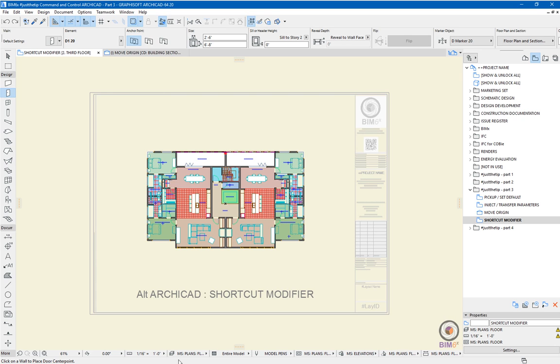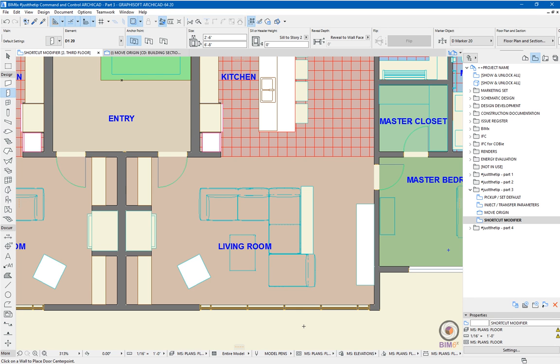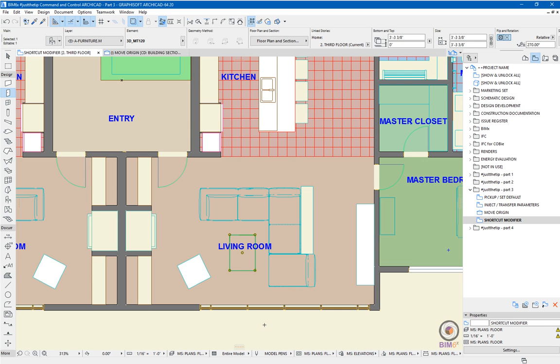Another one I use quite a lot, is probably the one I use the most, is to enable or suspend grouping. I've zoomed in on this area so you can see what this shortcut does. As I say, it's one of my favourites. If I select this table, you'll see it's selected individually, but it shows based on the corner points that this is actually part of a group.